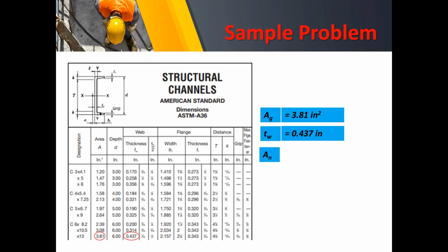So again, we will work with the net area instead of your net width, because on the first problem, we know the net width, but this time, what we know is the gross area. So we'll just have to note that your net area is just equal to the net width times the involved thickness.